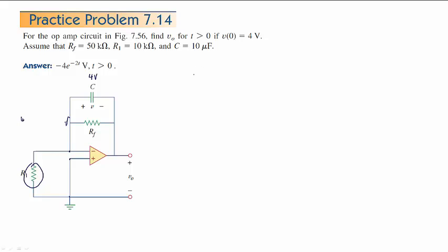We already know that the V right here, which would be V out, is going to have some kind of A e to the st form, and we have an R and a C together, and we can actually write that down. It's a discharging capacitor circuit, and we could write that down by inspection, knowing that this is 4 volts. Well, this point is 4 volts higher than this point, and this is at 0, so therefore that's at -4. That's its initial voltage, and we know that it's an e to the minus t over RC solution.